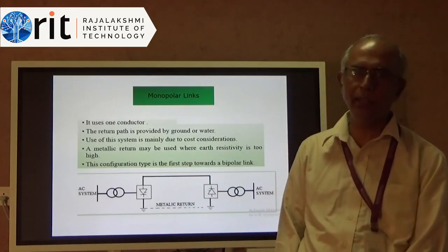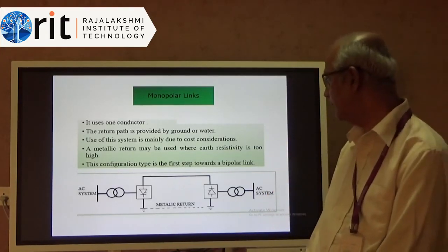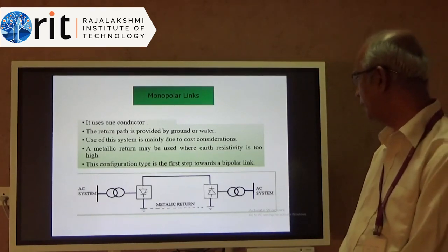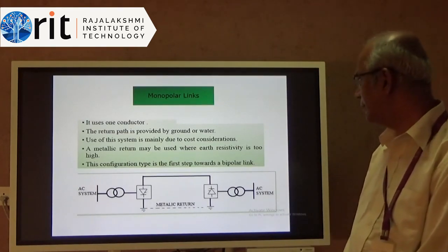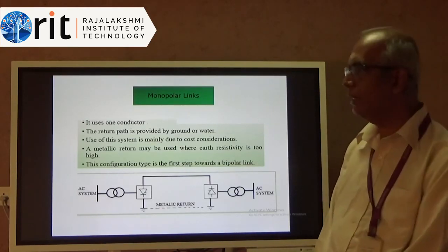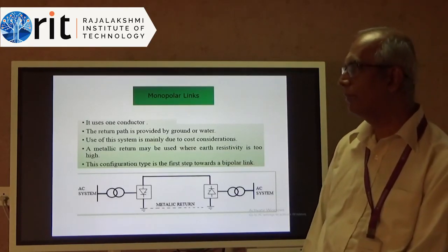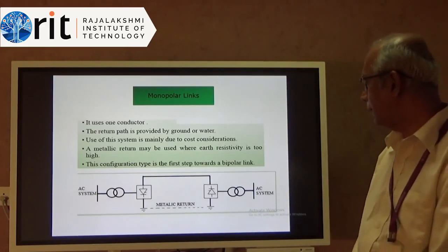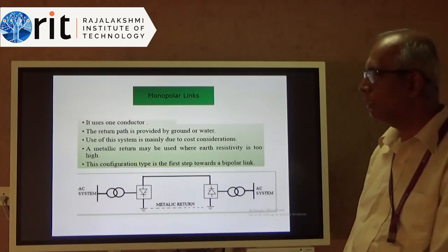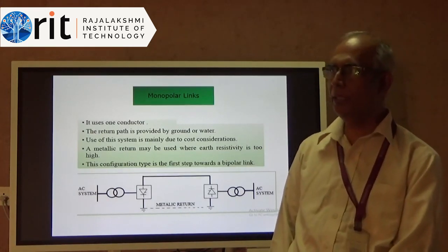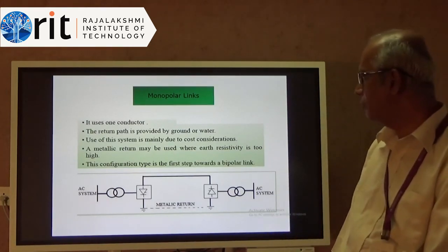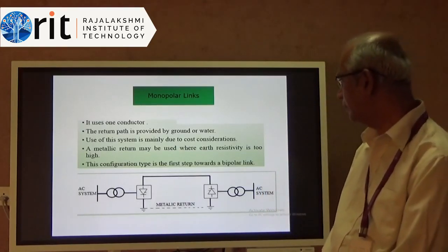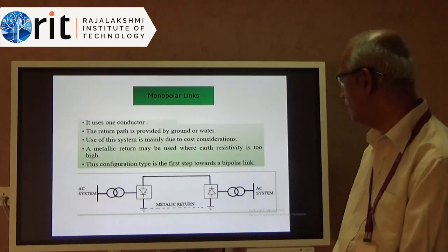Ground itself is a conductor of electricity. So, what we do is we have one single line running from the sending end to the receiving end, probably 500 kilometers long. Both at the sending end as well as at the receiving end, we do an earthing. Right? We just talked about an electrode. We do an earthing there. So, the return path is going to be through earth. Right? So, we say there's a lot of advantage because we are straight away reducing your transmission by 50%. Instead of 2 conductors, you are only having 1 conductor. There is going to be substantial saving in the cost.